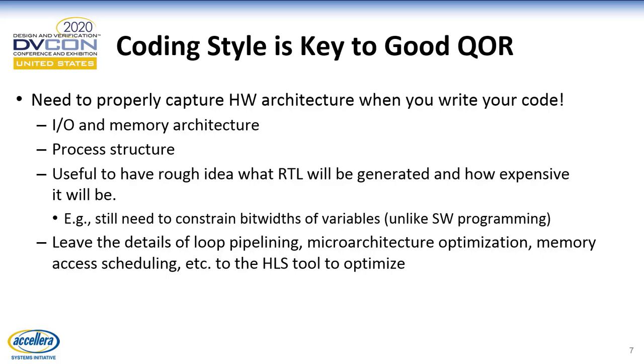So hardware is concurrent, software in general is sequential. And with a language like SystemC, we can explicitly express concurrency using things like SC threads, and we can express the concurrency in the design that we're going to want to have generated in the RTL, in the hardware.